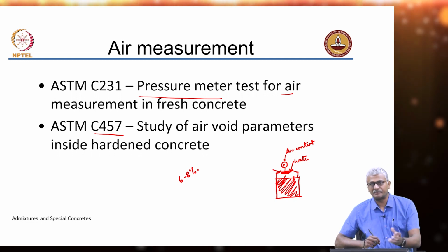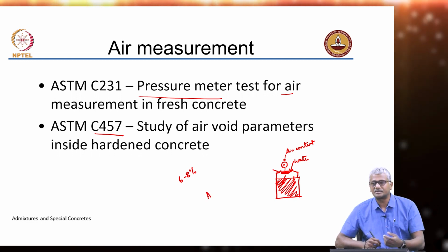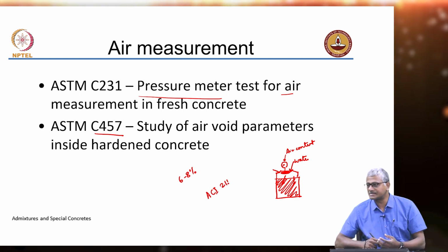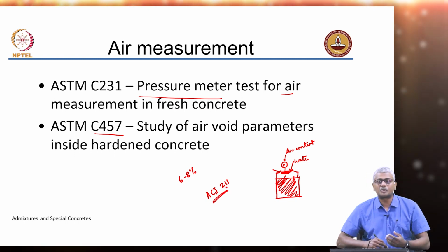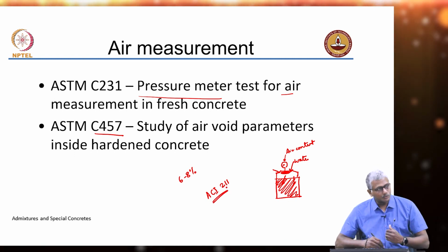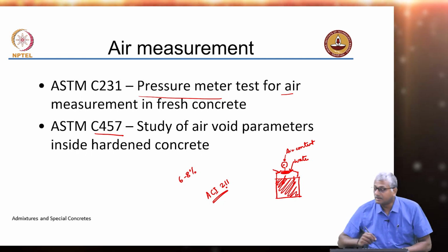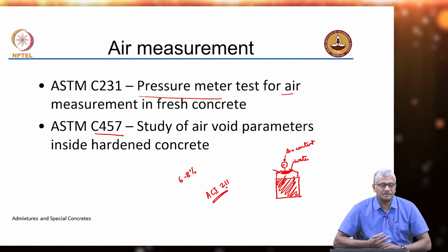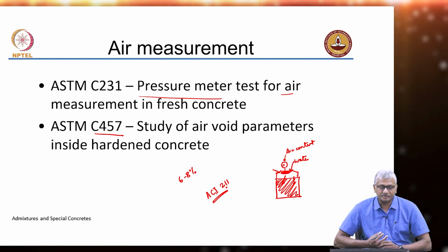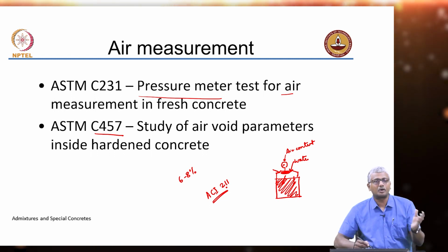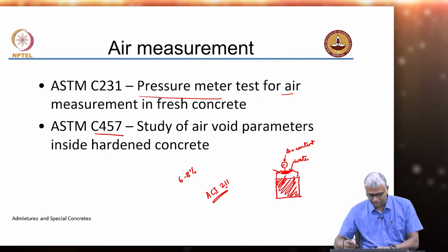When we discuss mechanisms, you will see that sulfate resistance especially is brought about by the fact that you use a cement with the lowest C3A content. The aluminate content is reduced to the lowest level in the case of sulfate resistant cement. There are also types 1A and 2A.